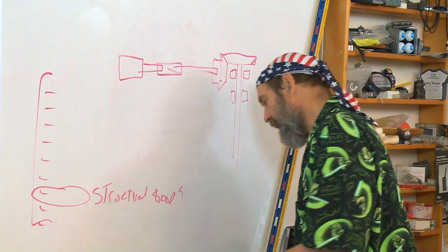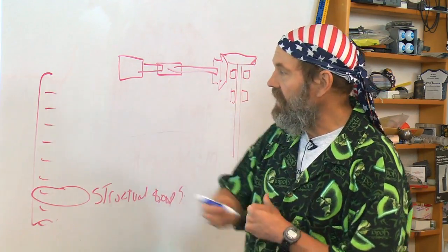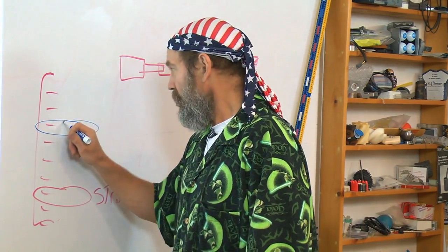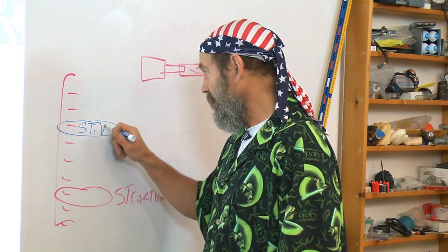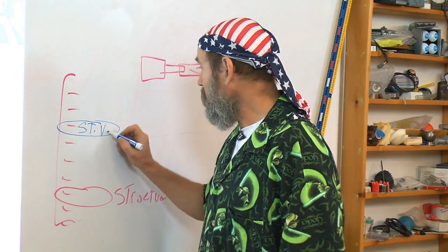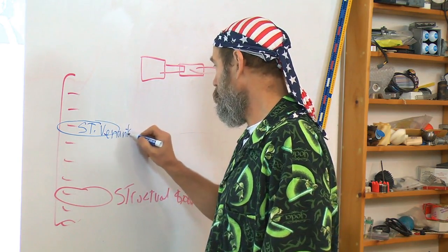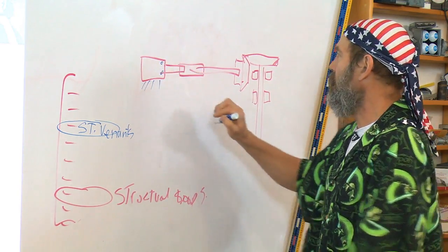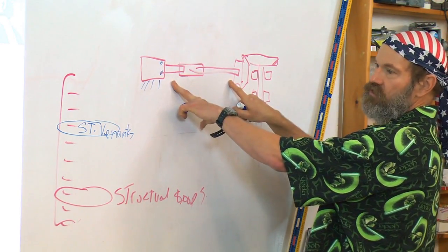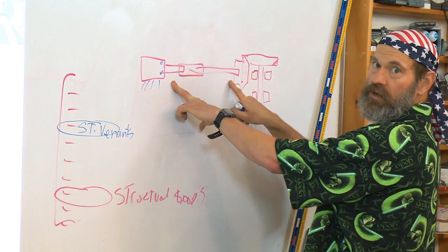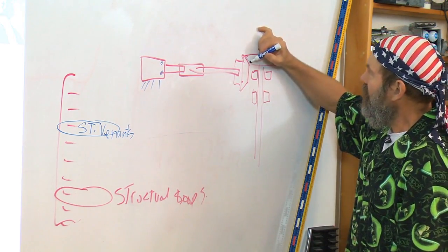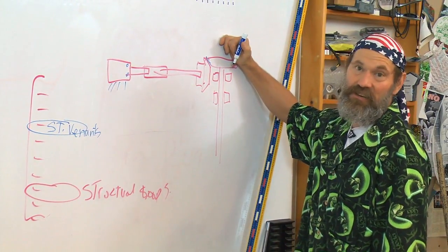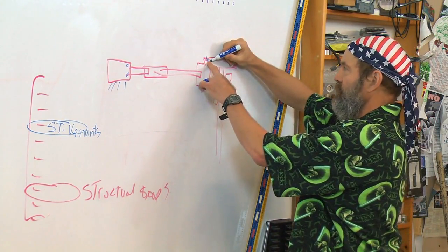And I know what you're all thinking. Ooh, I'm scanning up and down my fundamental principles. Ooh, and what he drew there, that really draws vacuum. That really violates, parentheses, it sucks, violates Saint-Venant's principle. Because here is the motor mounted here, and there are some bearings in the motor. And look at all this stuff here that's overhanging, that's unsupported. And you're probably also looking ahead to topic 6 with gears. And there are separation forces in the gear teeth.